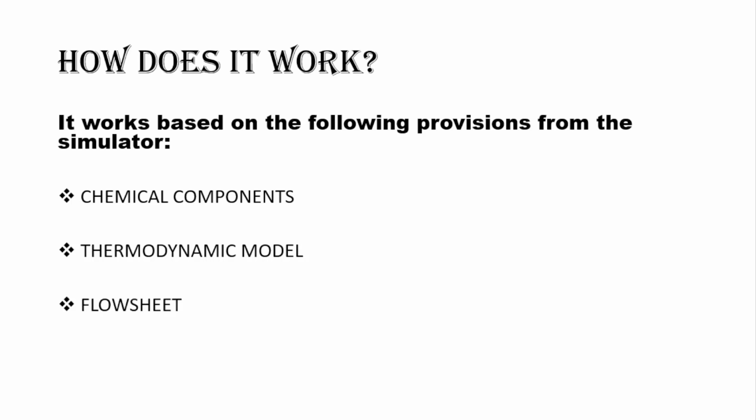All right. So after that, you have to provide your flow sheet, as I have already explained, and you have to give your process conditions. Process conditions are the thermodynamic conditions, the material stream conditions, and everything. So if you want to heat water, you have water in your stream, so you have to specify that it is H2O. You have to give a process condition to it.